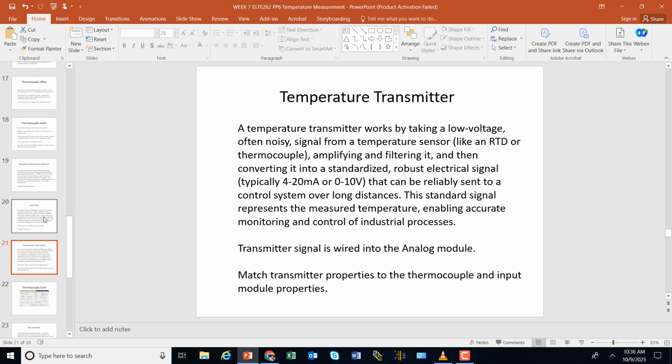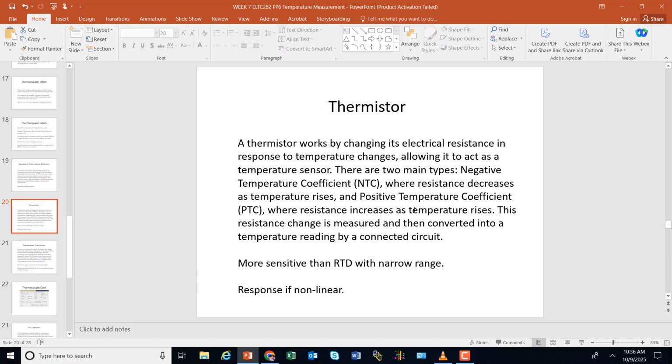Now, where might you see a thermistor? A thermistor might be in simple things like a refrigerator or your car AC. It's real basic, real simple, and they can use a thermistor. The temperature setting of your car AC doesn't need to range from absolute zero up to 2,000 degrees. You don't need to be measuring with a thermocouple. So there are applications where a thermistor can be utilized, very simply like that.